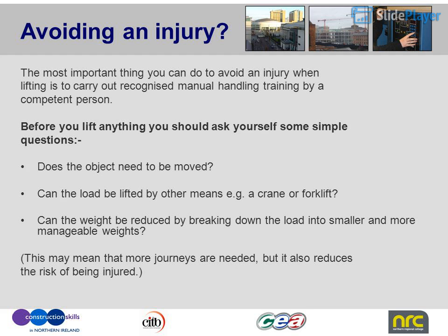Avoiding an injury. The most important thing you can do to avoid an injury when lifting is to carry out recognized manual handling training by a competent person. Before you lift anything, you should ask yourself some simple questions. Does the object need to be moved? Can the load be lifted by other means, for example a crane or forklift? Can the weight be reduced by breaking down the load into smaller and more manageable weights? This may mean that more journeys are needed, but it also reduces the risk of being injured.